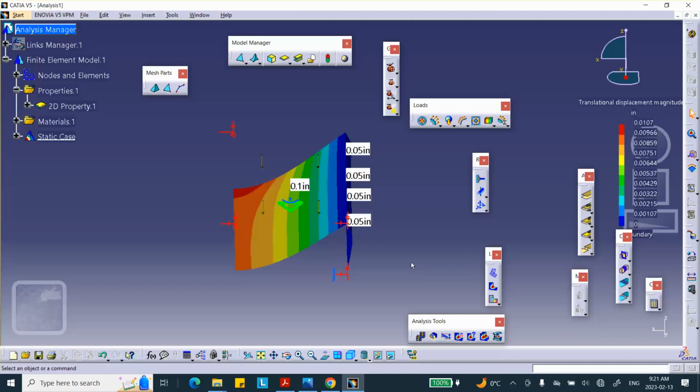So I'm going to repeat this in activity 4, except that I will create a box and extract the faces, and there you have to join, because if you don't join, when you mesh them, there will be duplicate nodes along that edge. I will show you in activity number 4.5 how to create analysis connections in order to tie them if you decide not to join those surfaces. Okay, so that wraps up this particular activity.